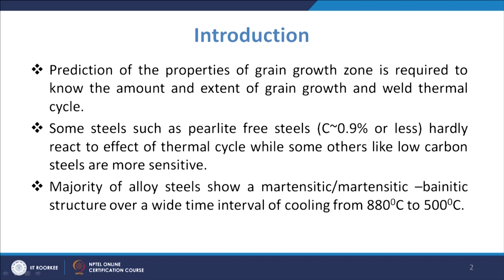The prediction of the properties of the grain growth zone requires knowing the amount and extent of grain growth and the weld thermal cycle, because properties will very much depend upon the change in grain shape and size. Grain growth is very much associated with the material being heated to a higher temperature during welding, and then cooled.